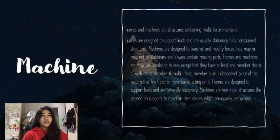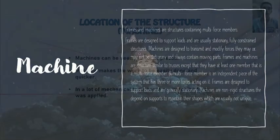Thank you. So the last one is machines. Frames and machines are structures containing multi-force members. Machines are designed to transmit and modify forces. They may or may not be stationary and always contain moving parts. Frames and machines are structures similar to trusses, except that they have at least one multi-force member. A multi-force member is an independent piece of the system that has three or more forces acting on it. Machines are non-rigid structures that depend on supports to maintain their shapes, which are usually non-unique.